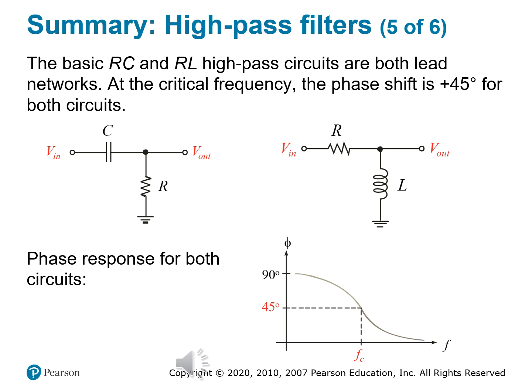And you look at the graph and see what it tells us. Again, looking specifically at the phase curve on the slide, as frequency increases, so does the phase shift. So it bends smoothly toward that 90 degrees. And at that exact midpoint, the critical frequency F sub C, you'll find our positive 45-degree marker. There's a symmetry to the low-pass filter phase plot, just flipped. Remember that lag becomes a lead.